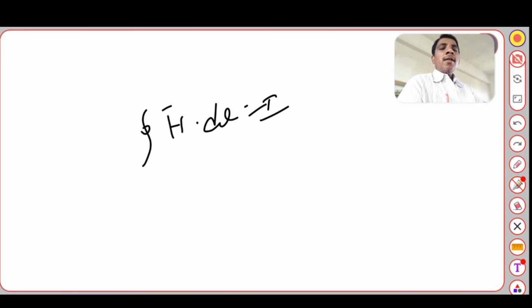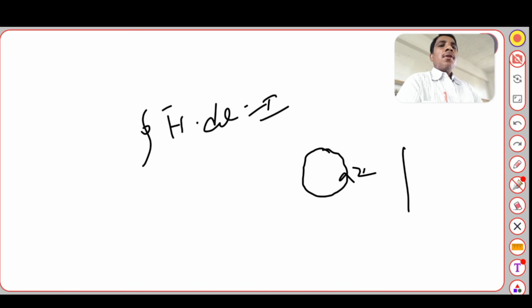The path enclosing the direct current need not be circular. The conductor may be an infinitely long straight conductor, and the law does not depend on the shape of the path. But the path must enclose the direct current once. This path is selected as the Amperean path. If you apply Ampere's circuital law, it is known as the Amperean path.